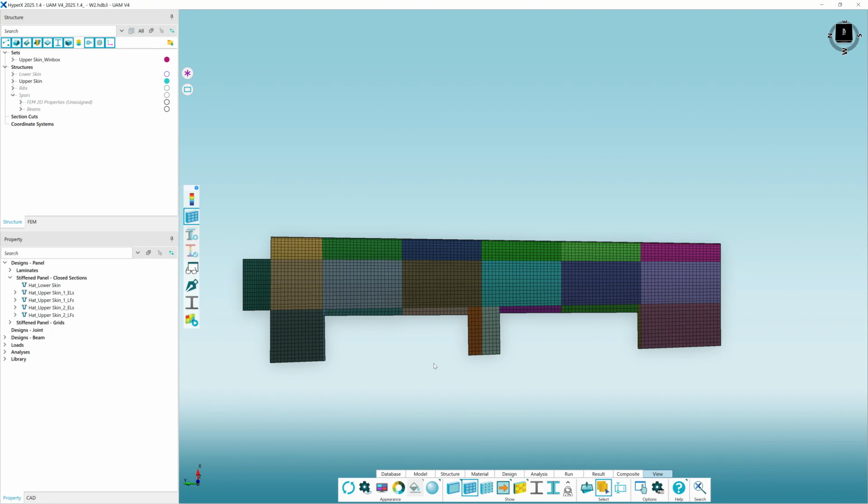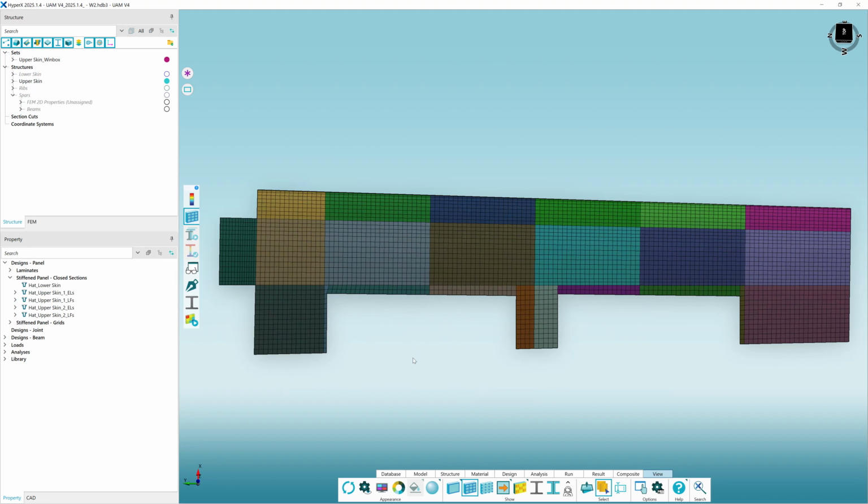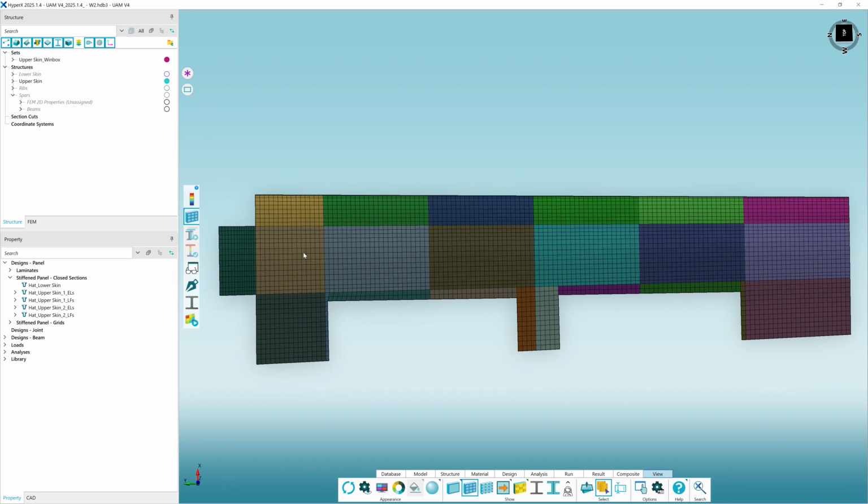The first prerequisite for generating that 3D geometry is the creation of something we call guide curves for the stiffeners. Again, there's no information in this model to describe the exact placement of a given stiffener. So based on our sizing results and our design property setup, we're going to create some curves that have a spacing that represents what's being analyzed in the structure.